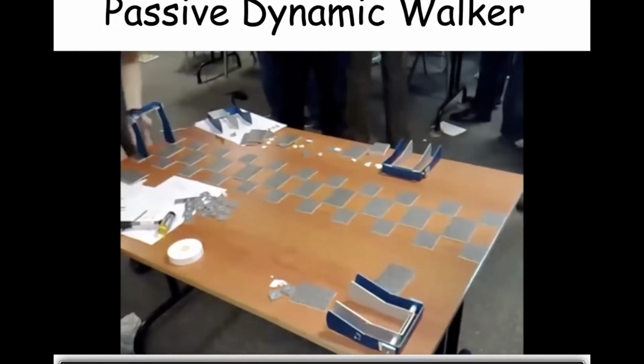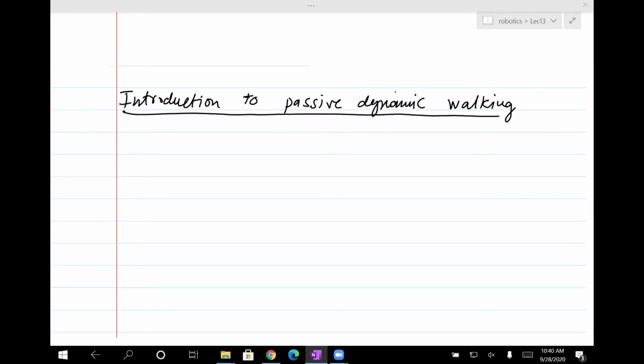That table is actually sloped downwards, and the gray patches are what is known as stepping stones. When humans walk, we basically don't have an issue of stubbing our foot on the ground when we swing our leg, and that's because we bend our knees. This particular walker doesn't have any mechanism to bend its knee because it doesn't have knees. So it's basically a straight-legged walker, and you need these stepping stones so that the leg can swing freely and not stub against the ground.